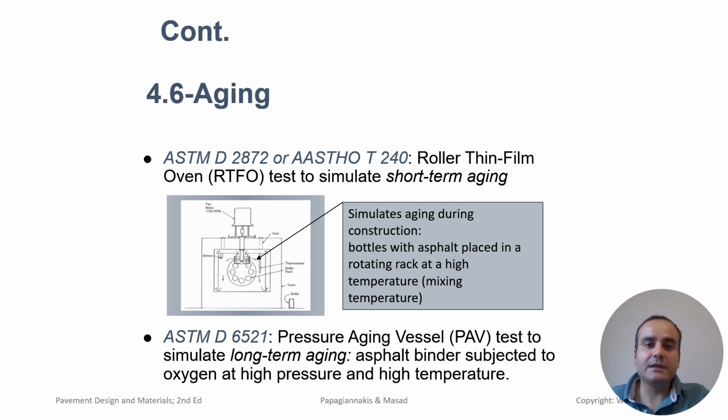The PAV test helps predict the binder's long-term performance, particularly its susceptibility to fatigue cracking and thermal cracking. By understanding both short-term and long-term aging behavior, engineers can select binders that remain durable and flexible over time.